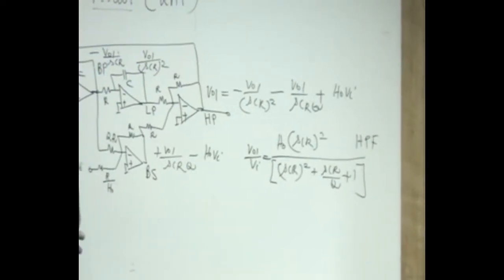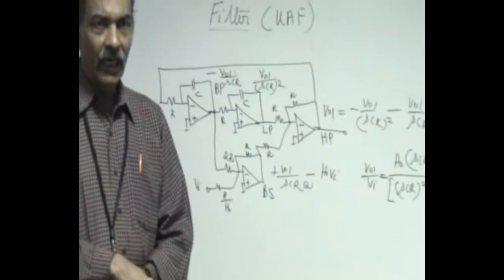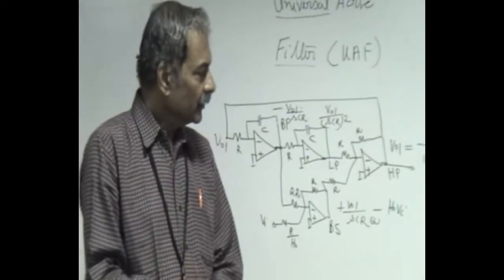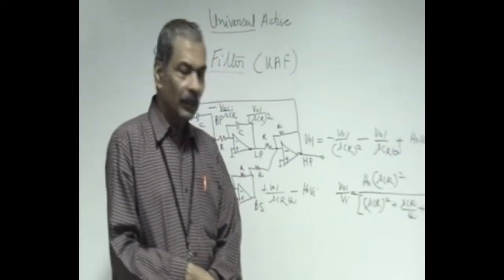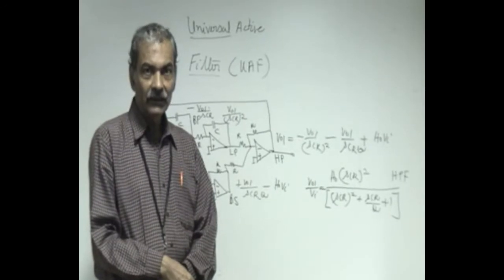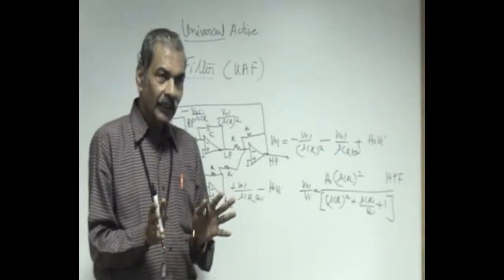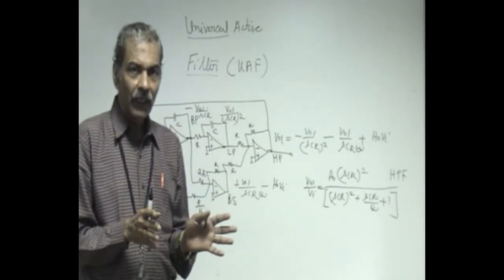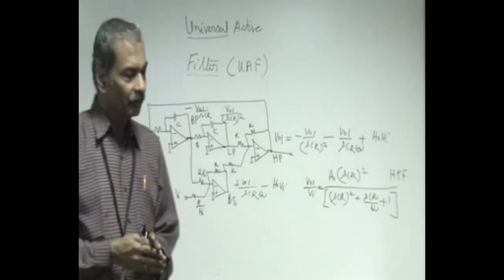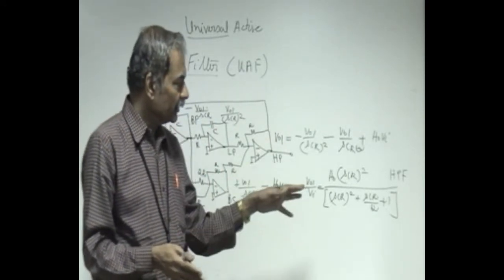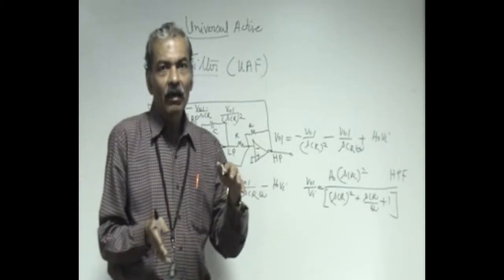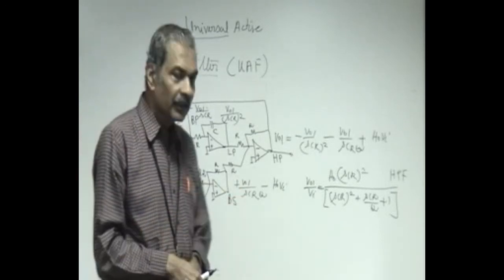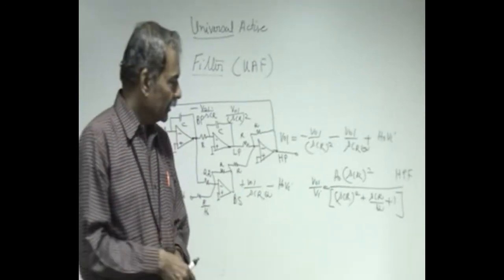If we have a first order filter, which is just using one R and C, we can get first order low pass or first order high pass. Along with that, we can now get a second order high pass. That means we can design any nth order filter as a cascade of one first order and any number of second order filter blocks. That's why understanding first order filter design and second order filter design almost completes the nth order filter design. By combination of these two orders, we can get any higher order.